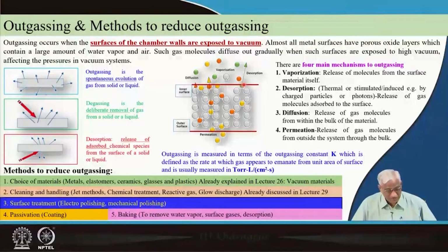And on the surface they are partially bound with some physical principles like van der Waals forces, etc. Then if you are trying to forcibly remove them, that is called desorption. But in the process, if they are just some sticky watery layers and they are coming because pressure is less than the saturated vapor pressure, they are called vaporization.